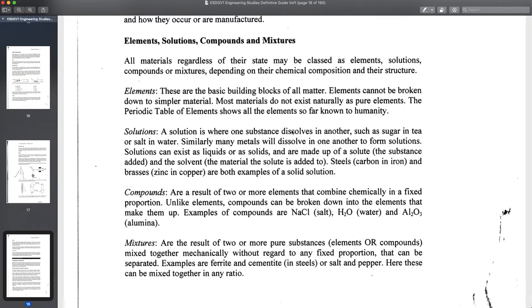The Americium shoots out radiation, and you have a Geiger counter, basically, something that detects radiation on the other side. When your dad cooks bacon in the fry pan and it starts smoking up the whole house, well, that smoke blocks the radiation. The radiation isn't being detected by the radiation detector anymore, and that triggers a circuit that starts beeping. Pretty amazing, right?